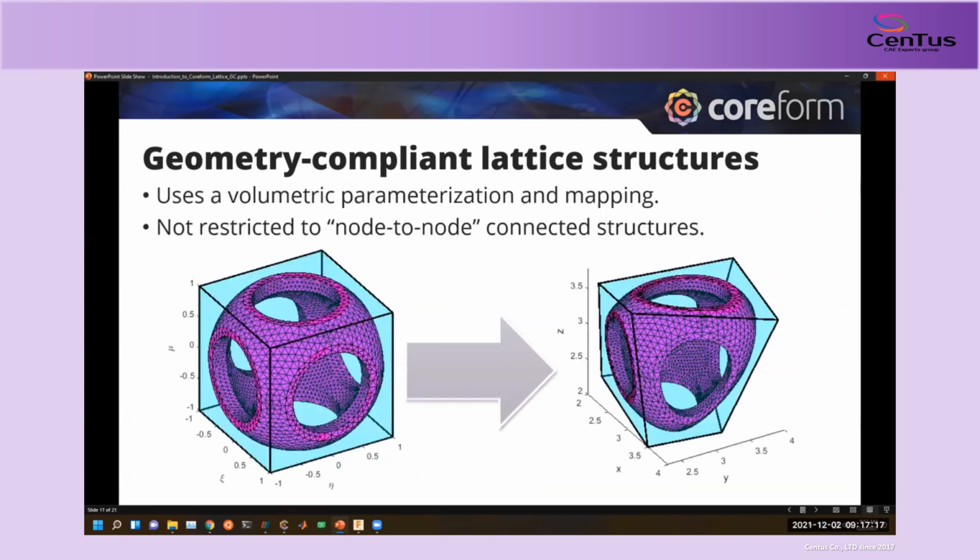And as a keynote, what's happening under the hood is we're just borrowing a lot of concepts from finite elements. So we take the geometric mapping of a finite element, and I've shown here the unit cell as a tessellation of triangles. Each point in this tessellation has a mapping to the element in its deformed configuration when you've meshed the part.